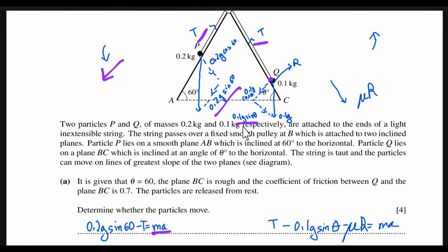So this is the weight and this is the power. There is a constant resistance to motion of magnitude 500 Newton. So this is the constant resistive force of magnitude 500 Newton. Find the acceleration, that is the value of a, of the car at the instant it has a speed of 20 meter per second. Before solving this question, you must remember the formula, that is driving force is equal to power by velocity. So we need to find the value of acceleration.